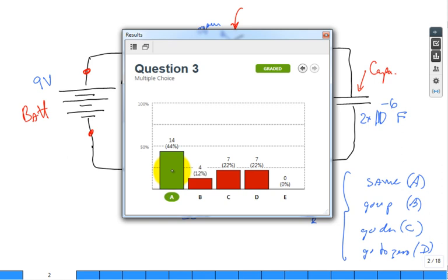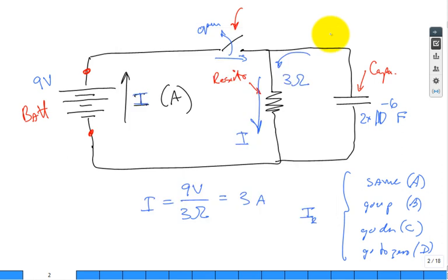It stays 3 amps. Now, let's say I wait a long time after the switch has been opened. And now, what is the current through the resistor? We can just do this verbally. Sounds like you got the best grasp of it. Tell me, what does the current do through the resistor? I open the switch. It stays at 3 amps, but then it's going to change after a long time, right? What's it going to do? It's going to go to 0. It's going to decay. And why is it going to go to 0? It's going in this loop right here. It's discharging the capacitor.